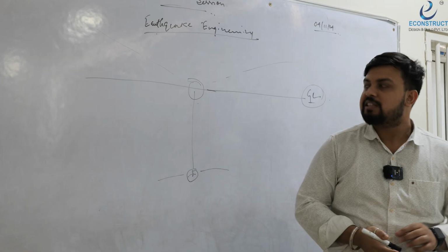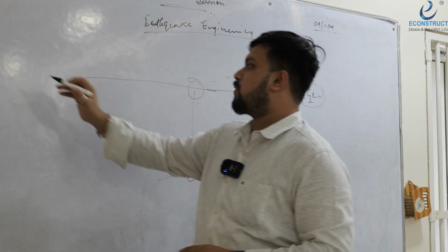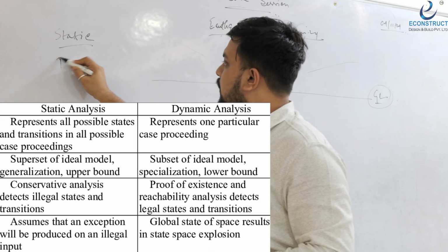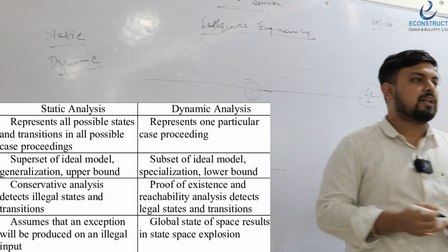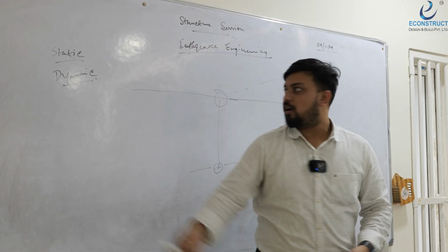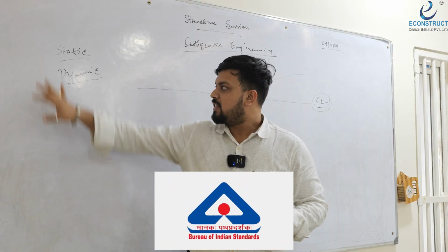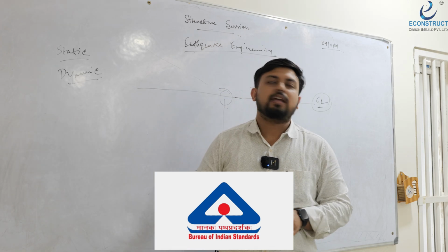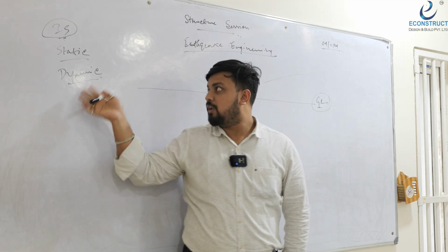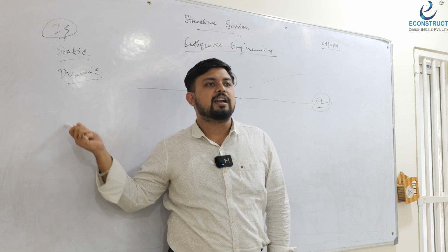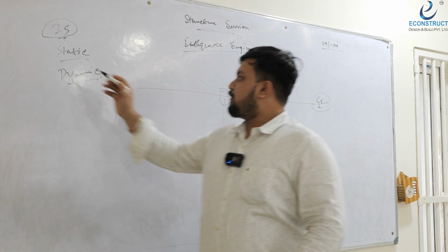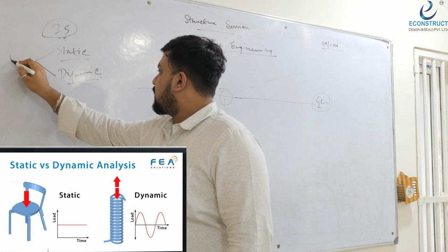Now in terms of civil engineering language, there are two kinds of earthquake analysis. One is static, another one is dynamic. Now we all know that earthquake is actually a dynamic force. Then what is the point of asking for static earthquake? So why have these two parts been told by the Indian standard? Why do we need both analyses? Why can't we directly go for dynamic? So the basic difference between these two is time period.